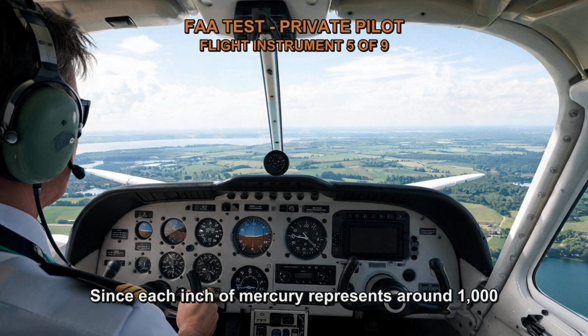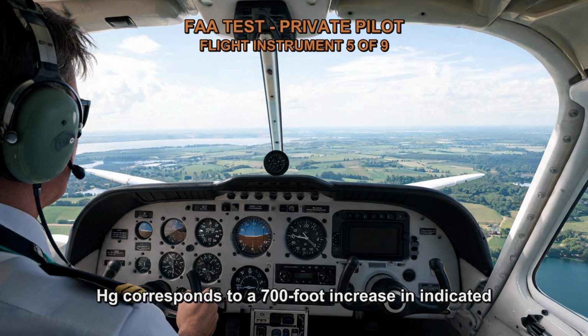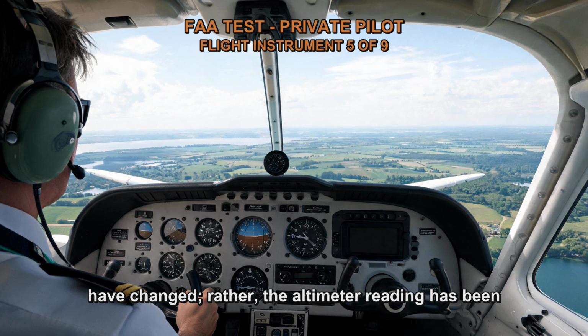Since each inch of mercury represents around 1,000 feet of altitude, a change of 0.7 in Hg corresponds to a 700-foot increase in indicated altitude. The actual altitude of the aircraft may not have changed. Rather, the altimeter reading has been adjusted to account for the change in barometric pressure.